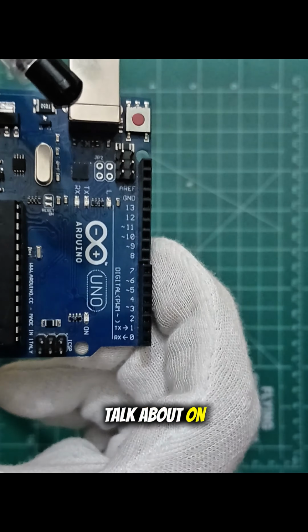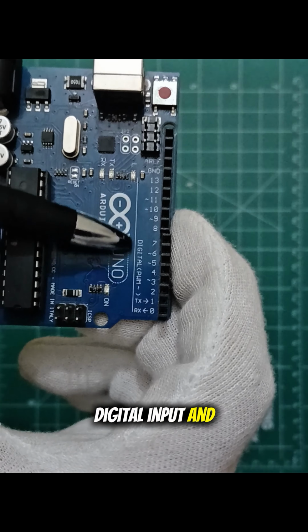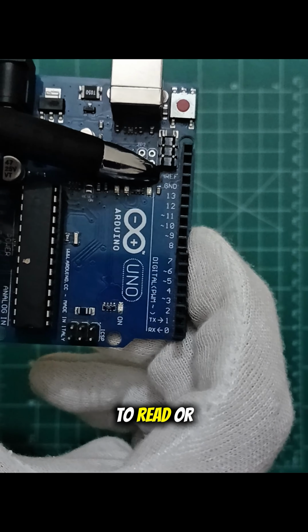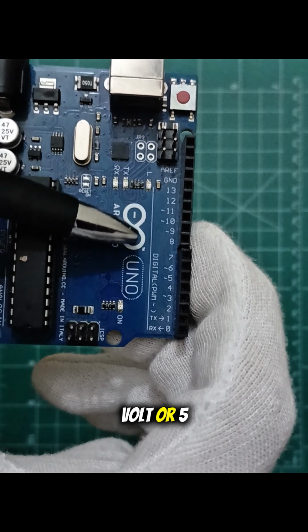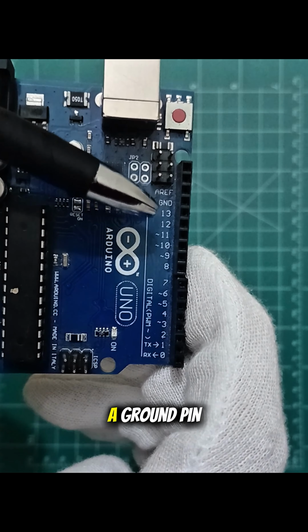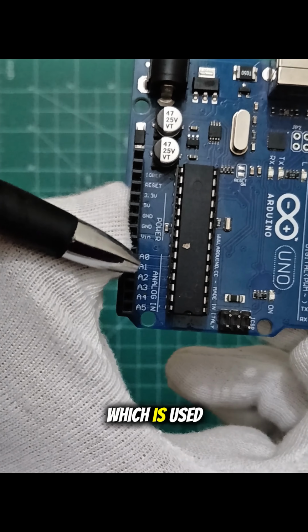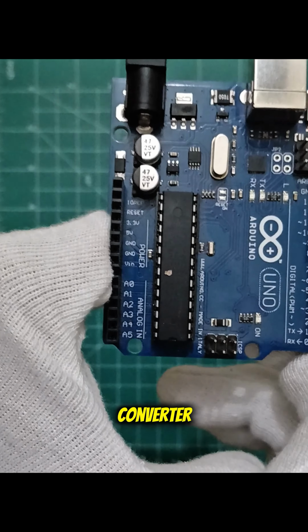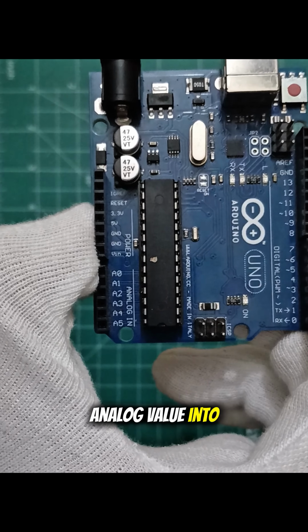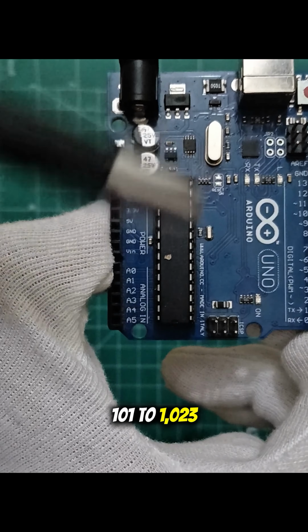If we talk about the pins on this Arduino, there are 14 digital input and output pins which are used to read or write digital values. Values that can be either 0 volt or 5 volt, and there is a ground pin as well. Then there are the analog pins which are used to read analog values. There is an ADC, an analog to digital converter, which converts analog values into digital values between 0 and 1023.